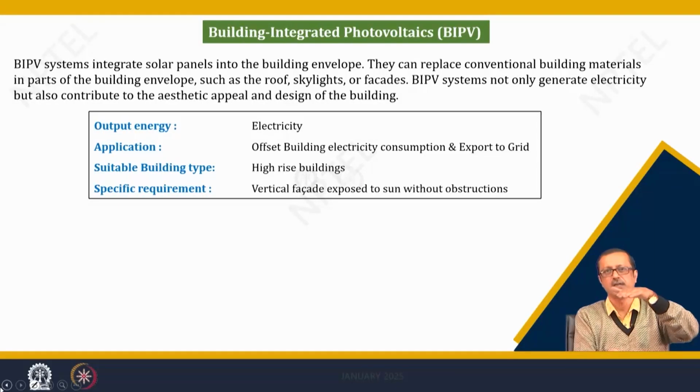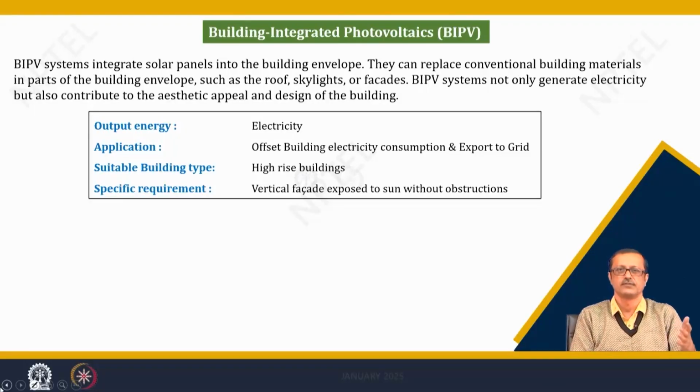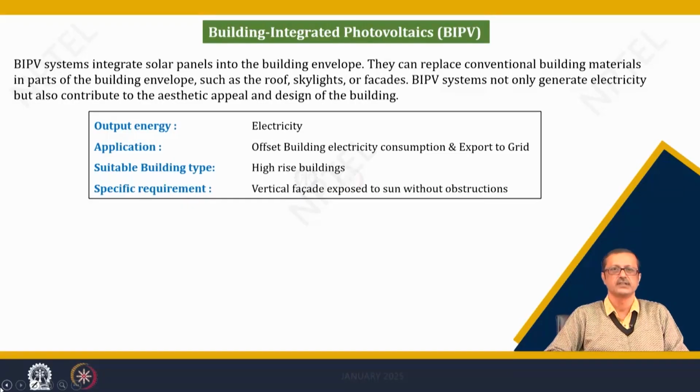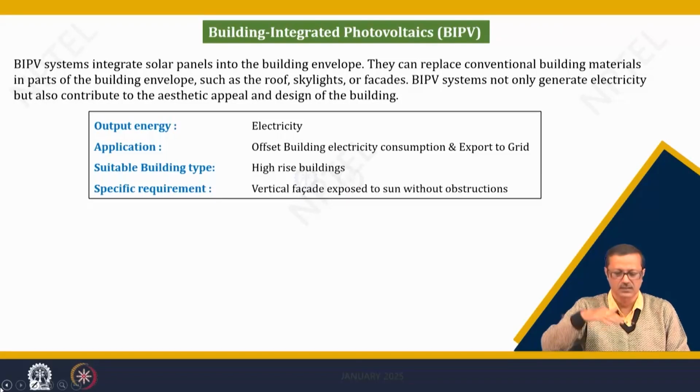So, for a 3-storied building, it is maybe 9-10 meters. For a 5-storied building, it is 15-17 meters. So, as and when the building goes higher, I will get more potential surface area, and I can have more generation, which is needed to take care of zero energy or something like that, to take care of the balance. But if I only bank on rooftop solar, I cannot increase the surface area even if I increase the number of floors.